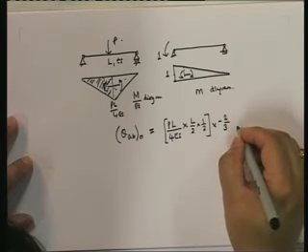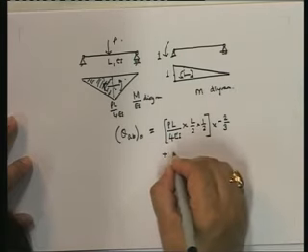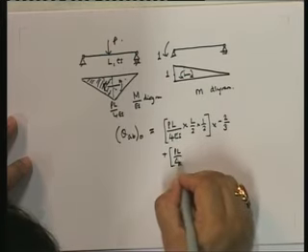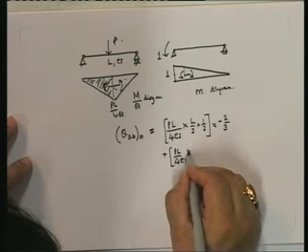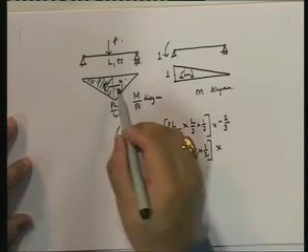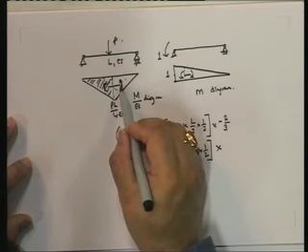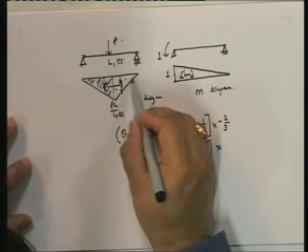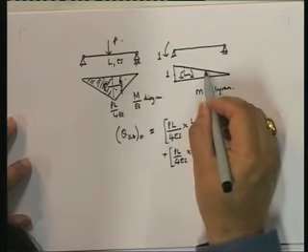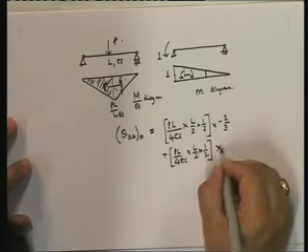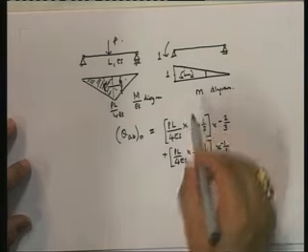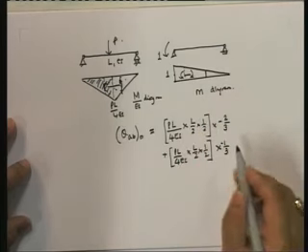And plus, then I have to consider this part. So it's going to be PL upon 4 EI into L by 2 into the centroid value at this point. Again 2/3 of L by 2, that's 1/3. So the value at this point is equal to 1/3, and again negative, because if this is positive, this is negative.